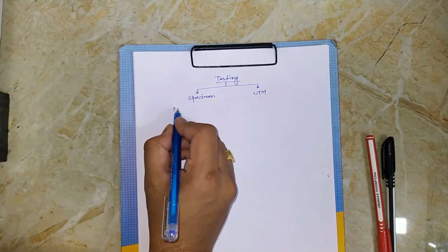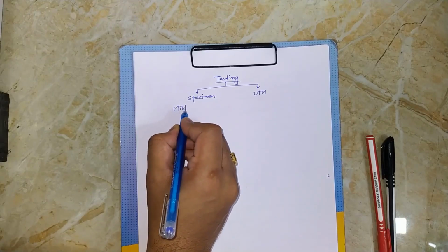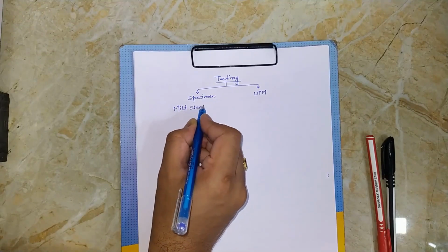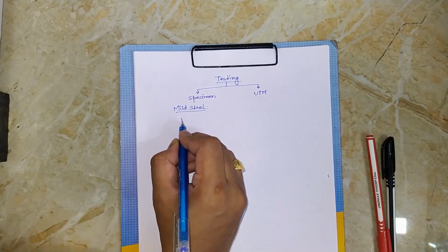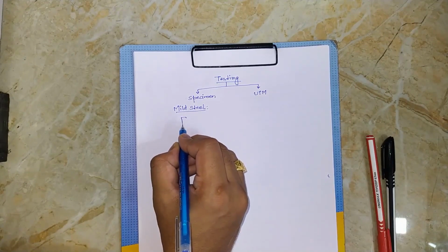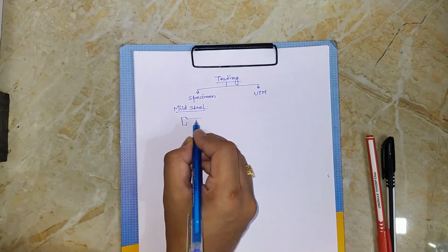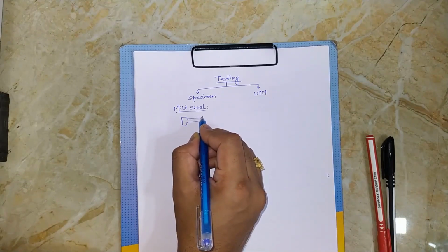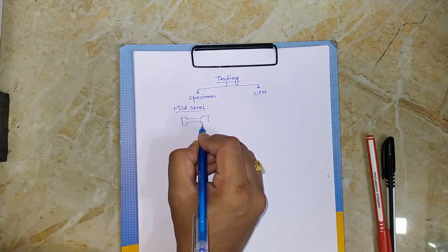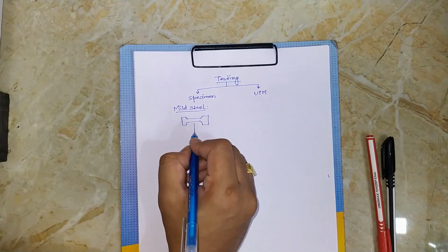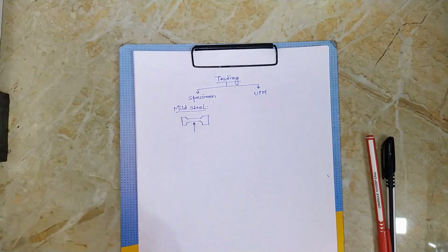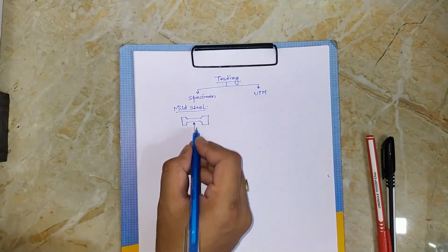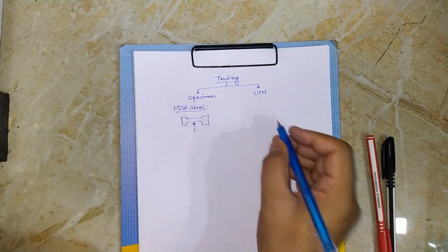Here we are going to see the stress strain diagram of mild steel, for which we'll use a dog bone specimen. A dog bone specimen looks somewhat like this, which has flattened ends and a uniform cross-section area to ensure that failure occurs in the uniform cross-section area, for us to have an easy visualization.